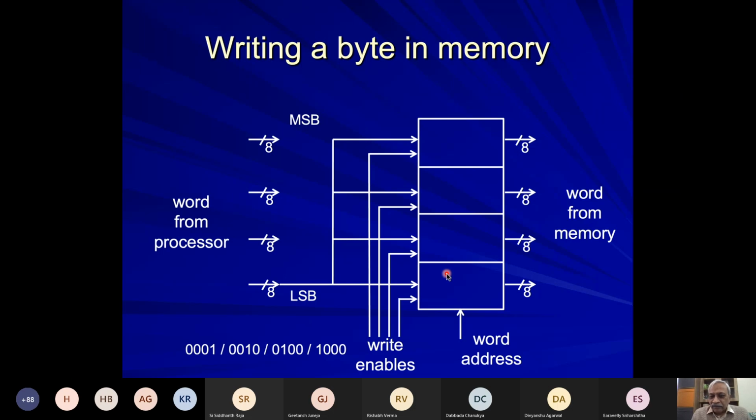Whether it has a write enable for the entire word, a single write enable, then you need to have read followed by write. If it has a write enable for each byte part, then you can do it in a single shot, just modify 1 byte.